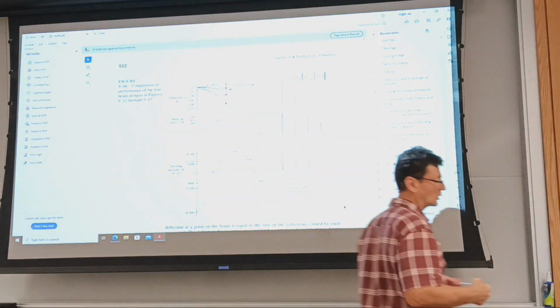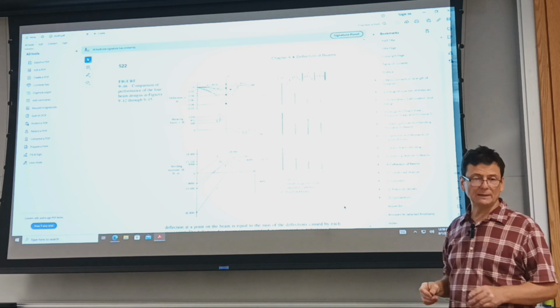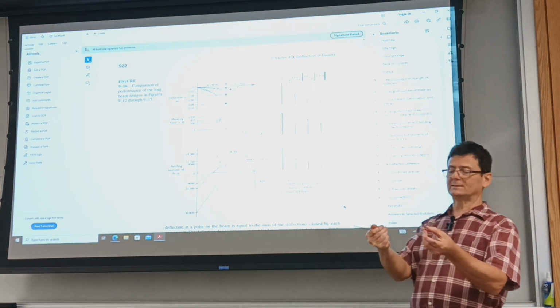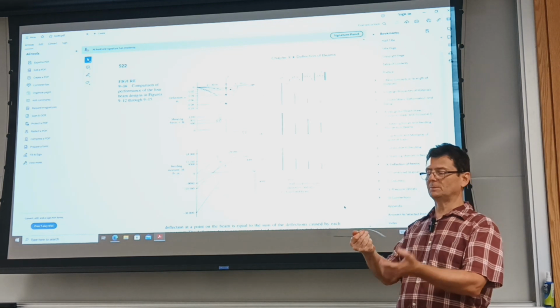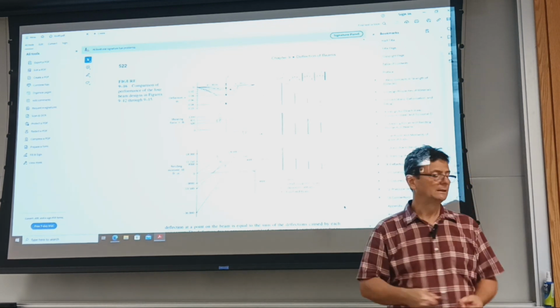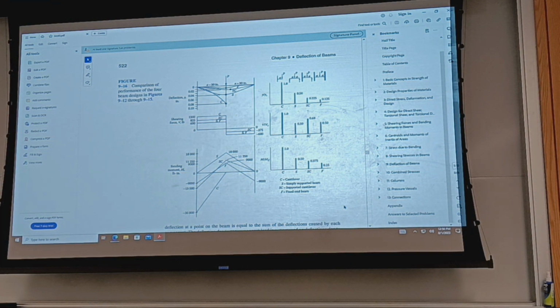And then you can work with the area property. That's why I-beams were devised, and we recognize that a flat rectangle is flexible, but if I rotate it 90 degrees, it is much stiffer. And then, of course, the ultimate last resort, you can change to a stiffer material. And I gave you the example of boring bars used on machine tools, on milling machines and boring mills.